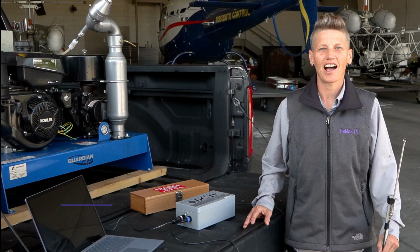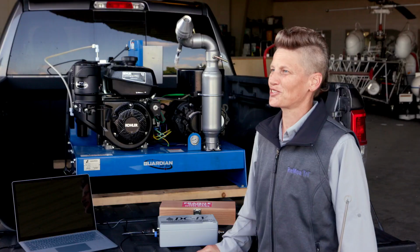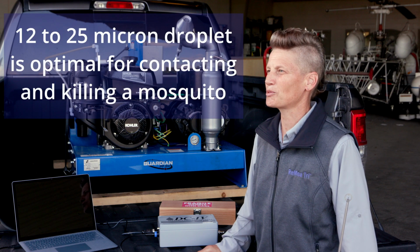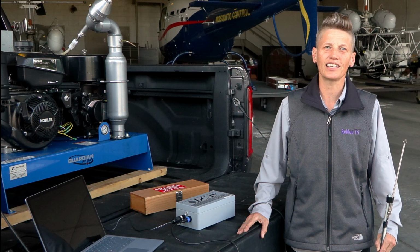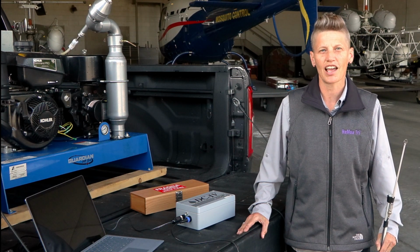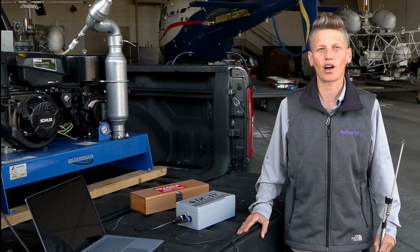Welcome to the field. I'm Leanne, and today we're talking about conducting droplet characterization on all of your ground ULV adulticiding equipment. The literature tells us that a 12 to 25 micron droplet is optimal for contacting and killing a mosquito. So it's important to validate that your equipment is set up to produce as many of those optimal droplets as possible. The required droplet spectrum is listed on the product label.